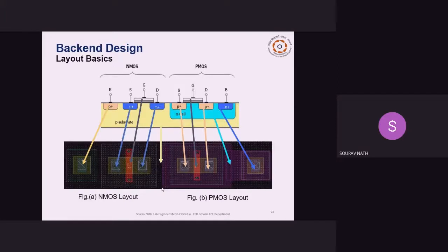This picture will give you more clarity. This is the PMOS, and the NMOS via for body biasing. You can see I have mapped the layers one-to-one, and I have marked the source and body with colors. You can see this pink one is the N well, and this is the M1 N active via for connecting the body of the PMOS. So these are the basics of layout. We will be showing them in the layout demo.